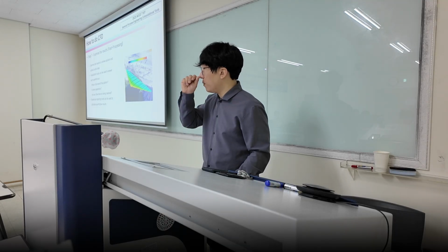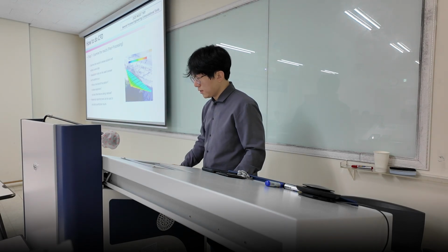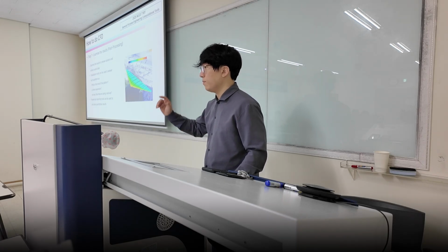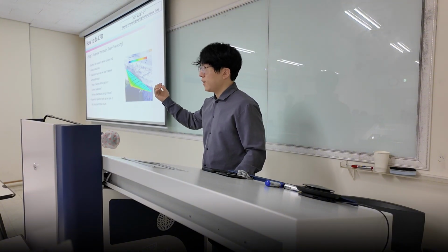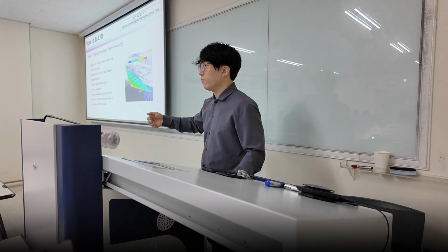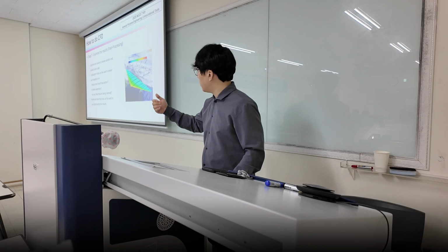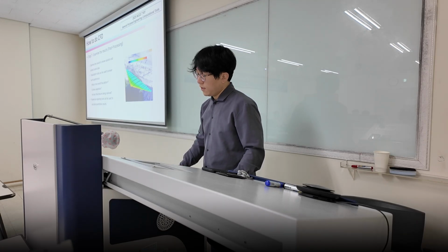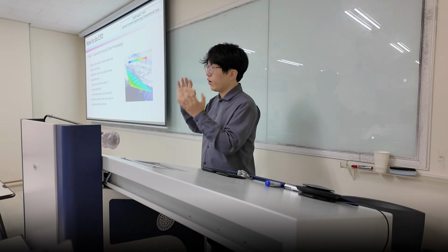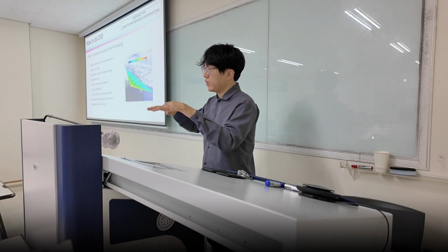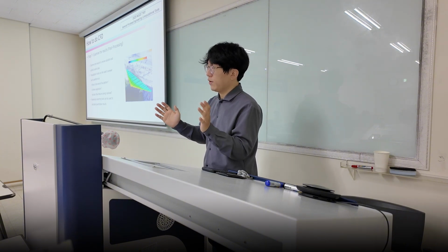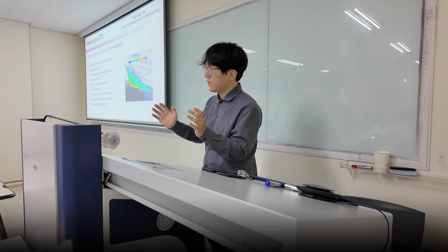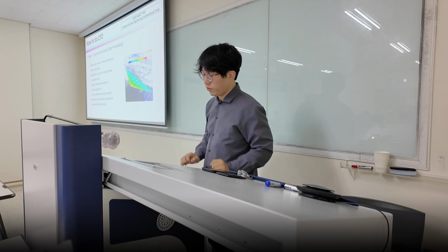One thing you can do is you can see the pressure displayed over the surface, but also what you can do is analyze the streamlines, and you can also plot the velocity field, or if you want, you can also display the temperature field, etc. as well. But you can't put everything in one figure because they're going to overlay on top of each other. So make sure, again, make sure of the solution you need and the phenomena you want to analyze. Really, really important.